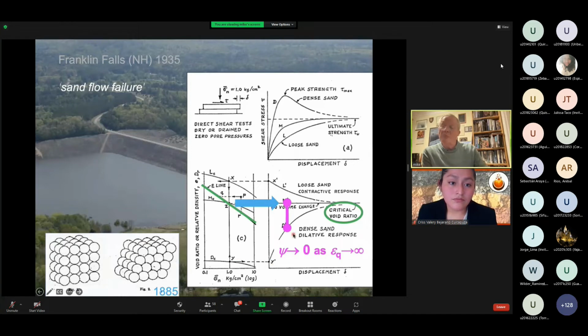And what we then say is, we can work with this mathematical idea, and we can now predict the stress strain behavior. So rather than doing a bunch of tests and saying these tests have some sort of magical property, we can say, actually, no, we can do the physics and we can go the other way around, and we will predict the stress strain behavior from a void ratio difference. And of course, the reason we like doing this mathematically is if you know your end condition, which is this thing here, then the mathematics become rather well controlled. I have to introduce you to one further idea before I give you the complete framework.